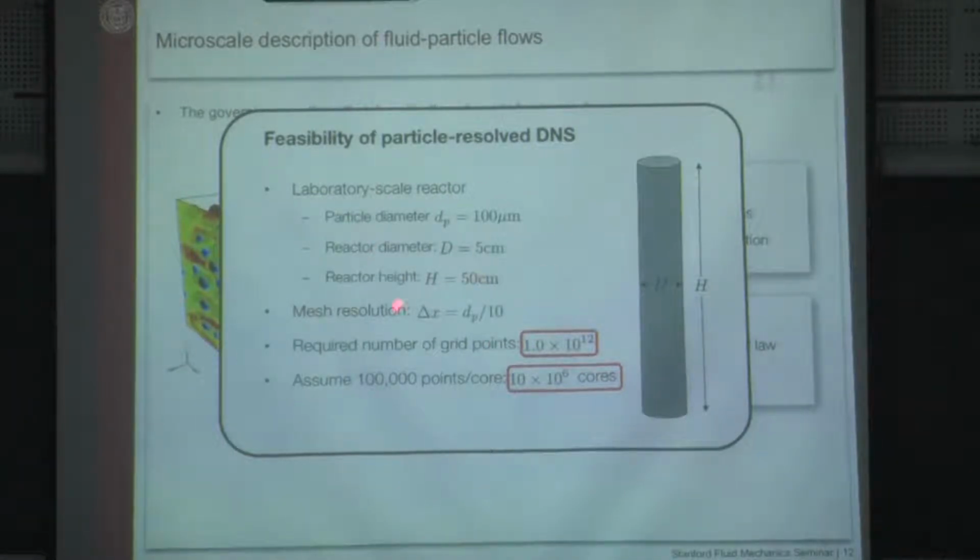then we've argued using an immersed boundary type of strategy, it's reasonable to expect that you need at least 10 points per diameter. You probably need more than that. But if you put 10 points per diameter, assume that the particles are essentially going to be space filling. They're going to be occupying pretty much every single region. There's no real opportunity for locally refining the mesh. So you're going to end up requiring essentially on the order of 10 to the 12 grid points to capture this reactor.